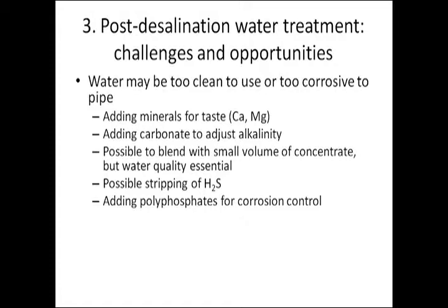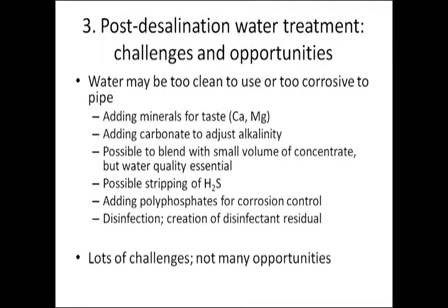You often have to add, because of corrosion control, polyphosphonates back into the water. And of course, you have to make sure the water is disinfected, and at least in the United States, we always provide a residual disinfectant in the water. And so all of these things represent costs and energy being spent to make the water useful even after you've taken all the salts out.